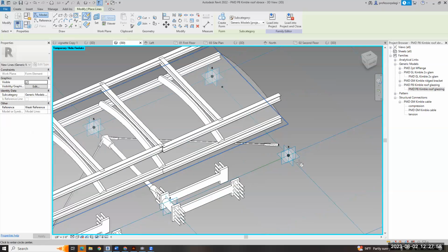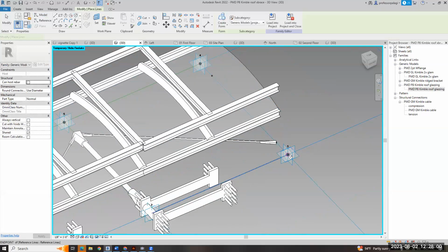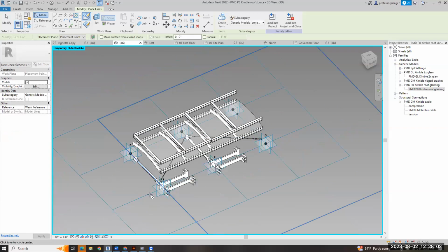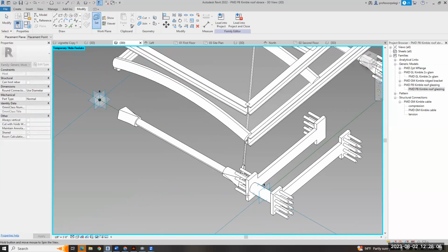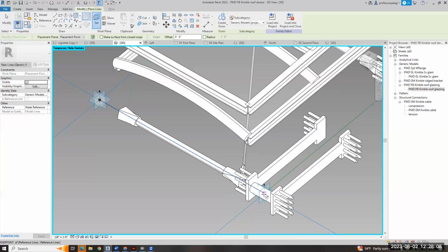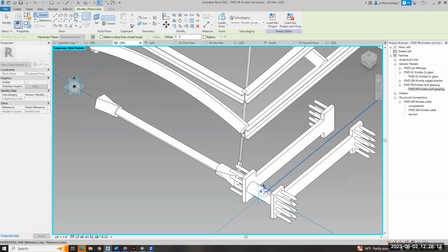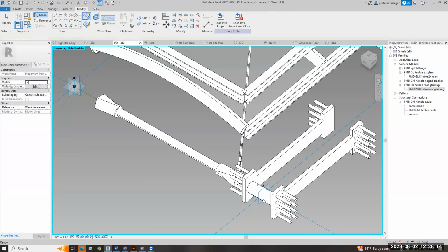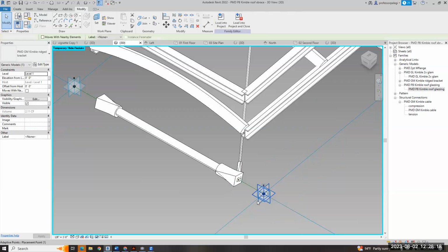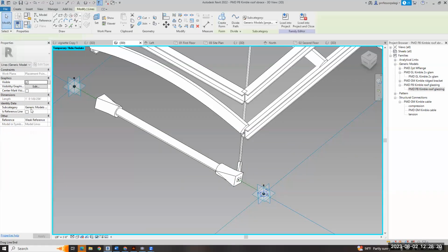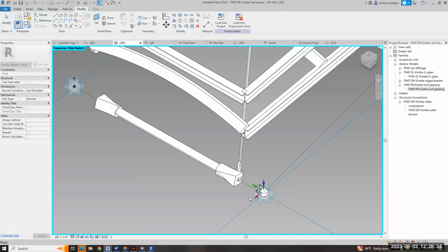I could just make an object in here, SW on that. Actually, SW on that. And I'm going to put a little 2-foot circle. Where'd you go? Let's hide this. So notice I'm going to make this a reference line, and I'm going to say create object, which is going to make a cylinder.